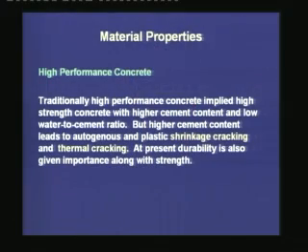Hence, when we are looking into the durability issues, we are not just interested in the strength, but we are also interested in reducing the shrinkage cracks so that we do not create any permeability in the concrete for the ingress of water and moisture.